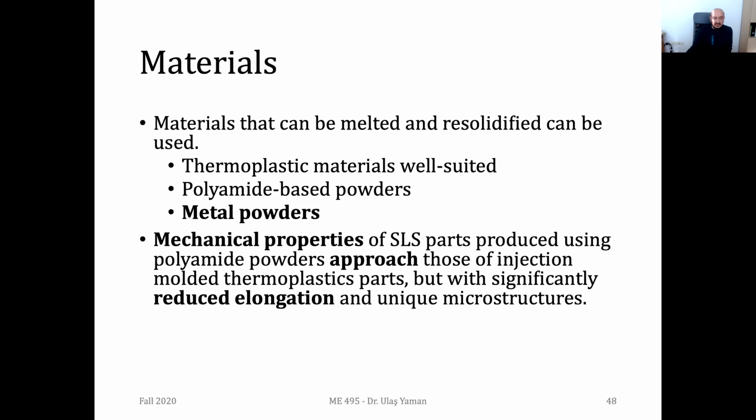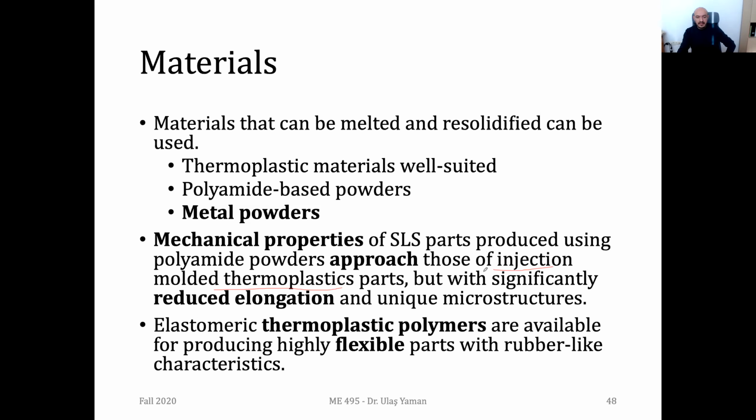And considering the quality of polymer-based parts, we have similar properties to injection molded parts. But the thing is that we have less elongation. Their elongation is not much. They are quite brittle, but their strength is somehow similar to the injection molded products. And these days, we also have some thermoplastic polymers, and they have flexibility. So if you want to have higher elongation, then you may need to use different types of polymers.